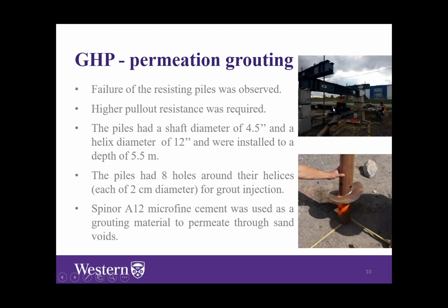In the middle of the test, we noticed that the piles were subjected to failure, and increased uplift displacement was observed. We didn't reach the required compression load for the micropile group. So we thought, how can we increase the capacity of our reaction piles here?